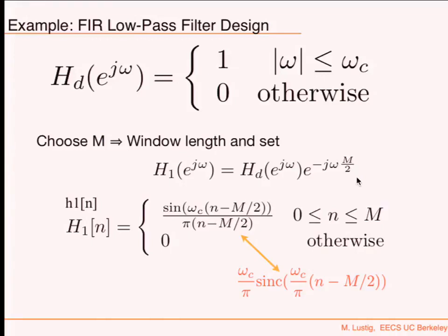Okay, I get that idea. So it moves the center of the sinc to the middle. Don't you want to move the center of the sinc off to the positive side? You don't want any negative. Yeah, I'm going to crop. So whatever is negative, I'm going to start from 0 all the way to M. But now my sinc is in the middle. So I'm always going to get the sinc in the middle of my signal. That's the idea. Because if I cropped from 0 to M and I didn't multiply by the phase, I'm just going to have half a sinc, which is not a good thing.